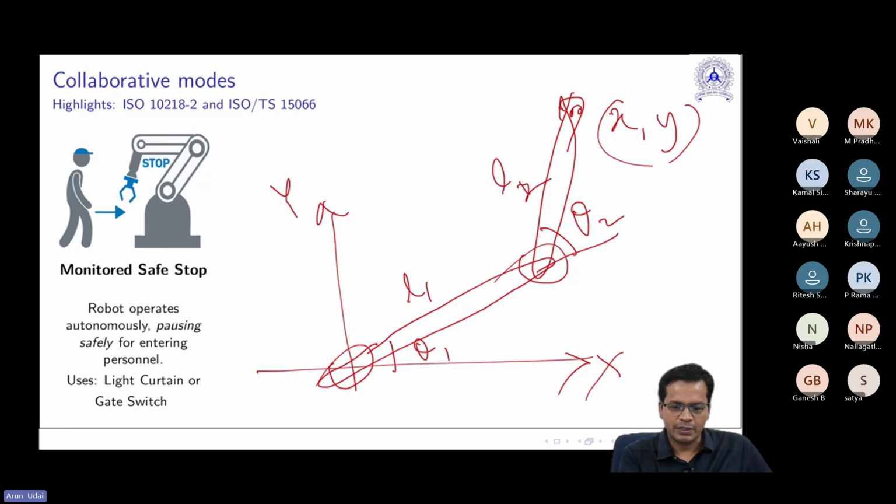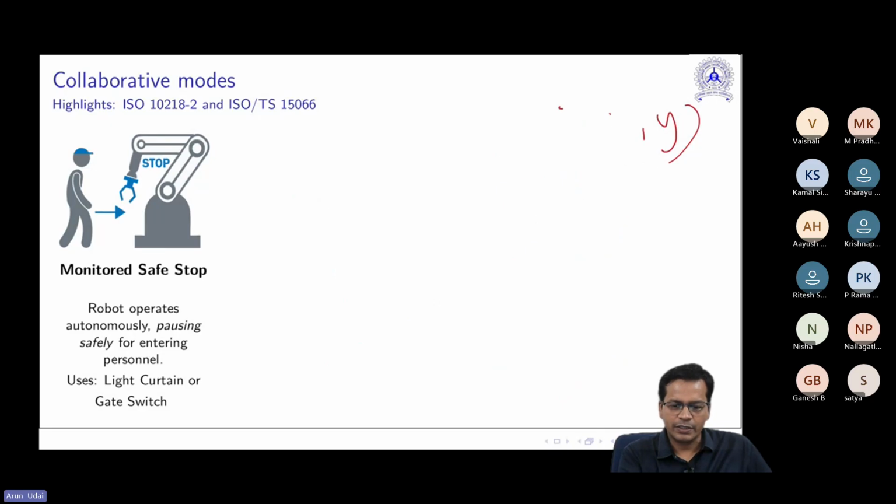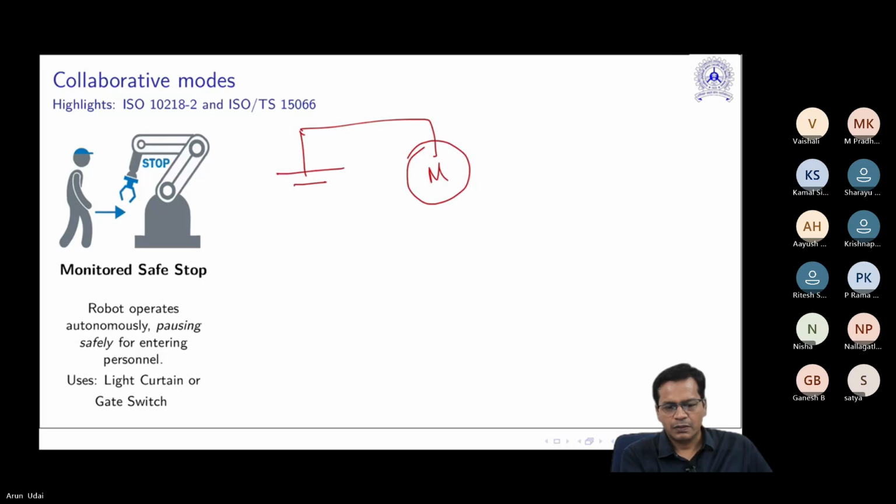Current control. Very simple, very easy. What you have been doing so far is this: this is your motor, and you are running it with the current flowing through this. Now, additionally, you put a low value resistance here.